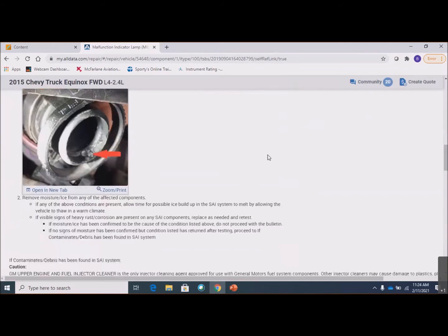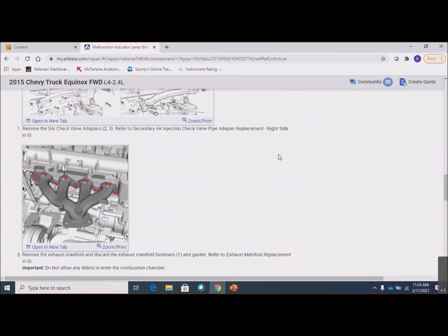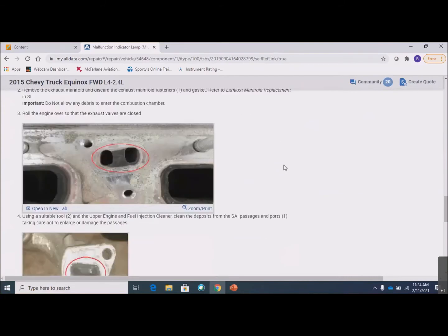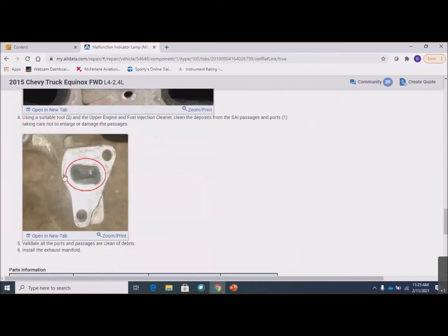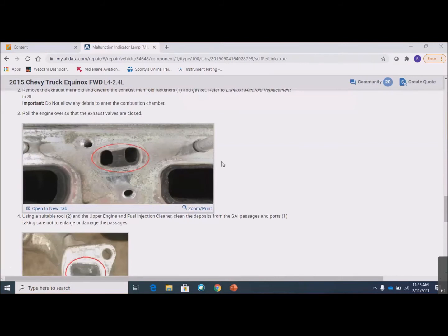So the next thing is to check these ports. Now, these are the ports in the cylinder head that I showed you a little while ago, and the tubes that feed the ports. And when we took this tube off, for those of you that were in for the beginning of this diagnosis, and then in the afternoon we got these tubes off, this is exactly what the tube looked like in the little manifold that feeds into this port here, right? Sort of plugged.